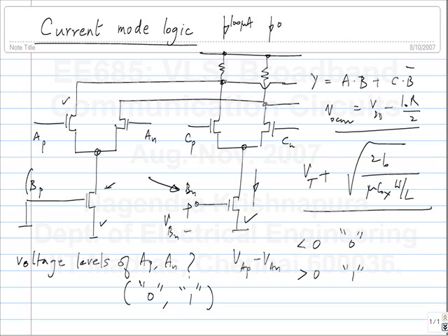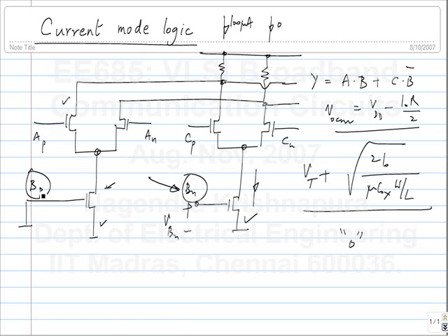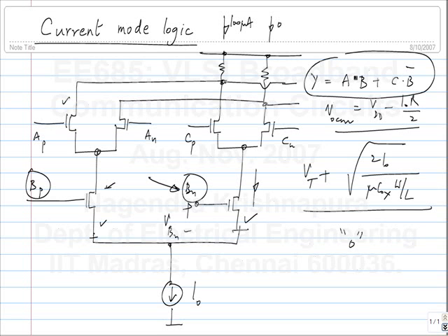These two are complementary logic levels, so we do the same thing we have done for the upper pair. Instead of doing this, if you do this now, what is the voltage level corresponding to logic 0 and 1 of B? Here also it is only the difference that matters. This ties in with the philosophy of using differential signaling. It's only the difference that matters, not the absolute value. So, it's also resistant to any common mode noise. This is how we need to do it. Now this does implement this function where A, B and C all are differential inputs.